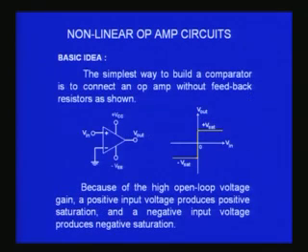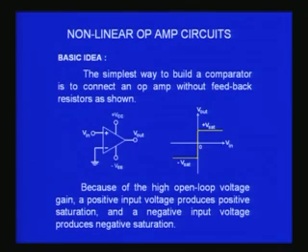Now what is the basic principle of this comparator? Let us look at this basic principle. We all know about the operational amplifier. When you do not use any feedback, negative or positive, it operates under what is known as open loop condition. Under open loop condition, without any feedback, the operational amplifier has very high gain. The typical gain of the operational amplifier that we keep using, the 741, as you all know, is 10 to the power of 5, 100,000.